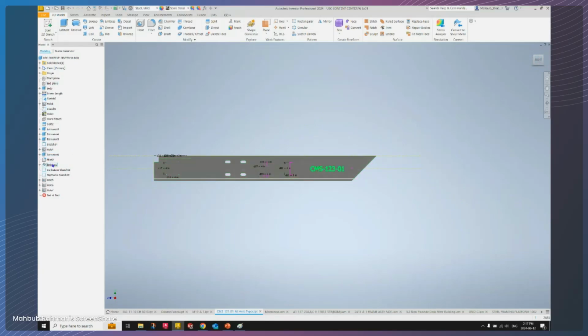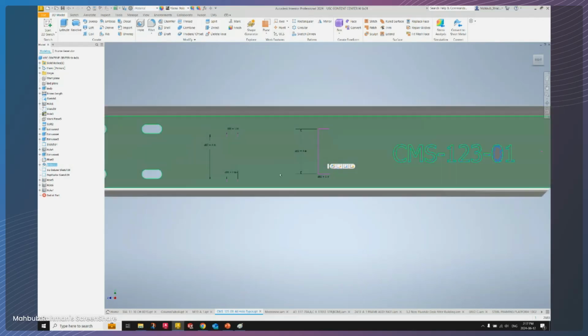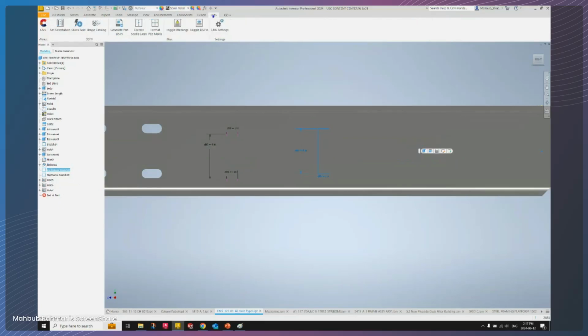So if you just go in on this design tree there, I see that I have an embossing feature. Just to show you that the software has the capacity to read the embossing feature as well. And at the same time, what I did here is I put an etching line here, right? So for example, if you want to bring that etching line to your NC file, you have to really let the software know which one you want to bring as an etching line. So you might have hundreds of unused sketches, right? Any sketch line that has not been consumed by a feature, we will be able to grab it depending on your settings. As you see, what I'm doing here is I'm highlighting that sketch line.